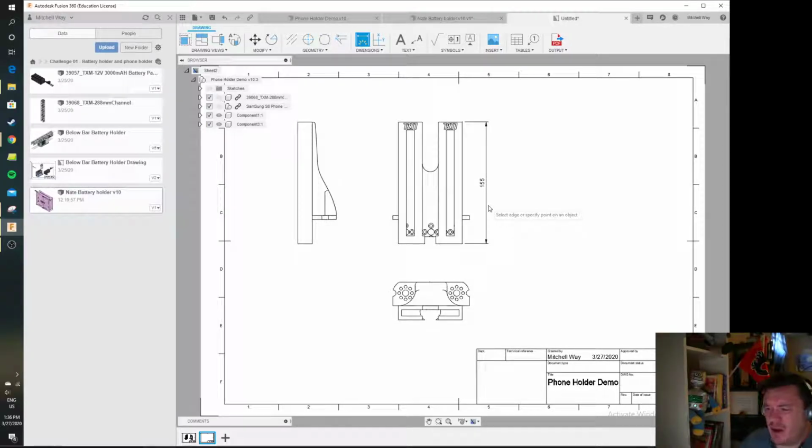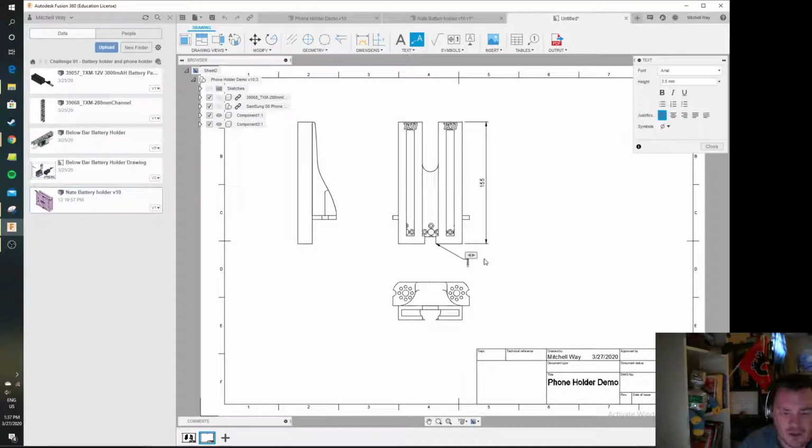This is really important if you're having parts machined, for example. If they're not coming off a CNC machine, they probably need to have dimensions on them, so whoever's making them knows how to fabricate them. At Nelson Mandela, we deal with this all the time because a lot of our parts get made up in the aviation shop, so we send them to students, and they're very used to the notation on this. Now, one of the other things you can do that I actually find hugely useful is putting leaders on. And if you look at this drawing in our folder, you can actually see that this is something that I've made use of.